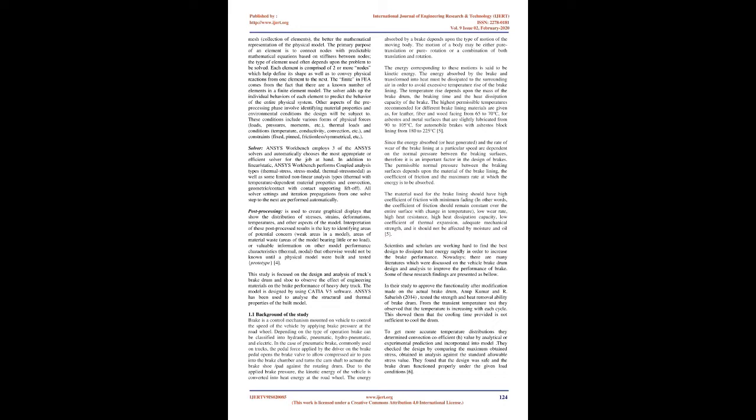The important requirements of the brake drum are the following. It should provide a surface having good anti-wear qualities. It should allow the optimum rate of heat transfer. Heat is generated during each brake application, and it must be dissipated to the atmosphere immediately, because the next brake application would again produce more heat. Any excess heating of brakes would cause the drum to expand, resulting in loss of effective pedal travel and fading of brake lining. It should have sufficient strength but minimum weight. It should be able to be accommodated within the wheel space available.